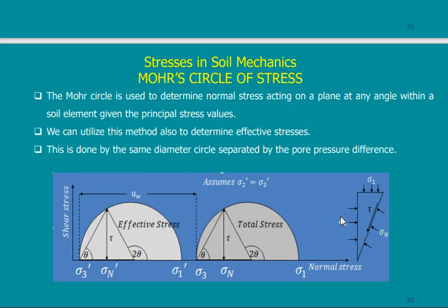If I have a foundation on the ground and this foundation is pushing the ground, then it wants to shear the ground, it wants to go down. So for the ground to move, the particles of the soil have to be sheared. So it's another type of stress. The first stress is the load divided by the area. This is a normal stress.